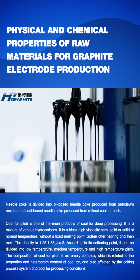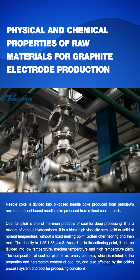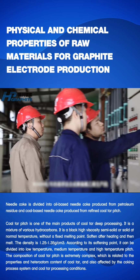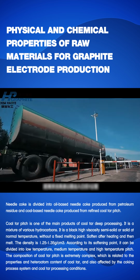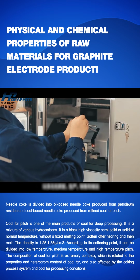The density is 1.25 to 1.35 grams/cm3. According to its softening point, it can be divided into low temperature, medium temperature and high temperature pitch. The composition of coal tar pitch is extremely complex, which is related to the properties and heteroatom content of coal tar, and also affected by the coking process system and coal tar processing conditions.